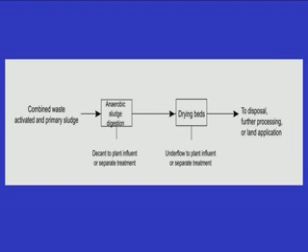And this is the third alternative. The combined waste from the activated sludge and primary sedimentation tank is coming, and again we are going for anaerobic digestion, and the plant effluent whatever is coming is going for further treatment. And here we are not going for any chemical conditioning, because the drying step is not centrifuging or belt filter press, we are using only drying beds. In these drying beds, we are allowing the sludge to stay there for a long time.